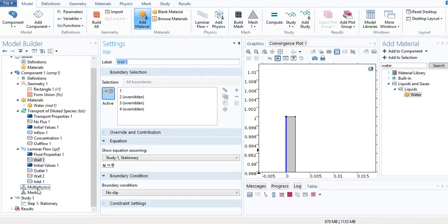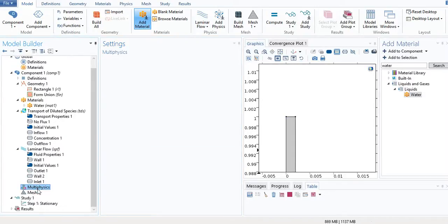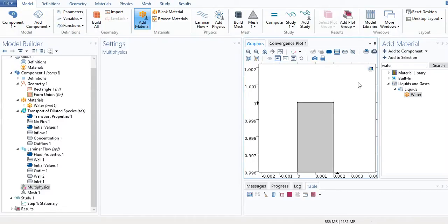In the classroom we did that by drawing a volume element. We need to couple or link the mass transport and the momentum transport equations. So far, Comsol will view each set of those 2 equations as separate entities. So we need to ask Comsol to link them or to couple them.